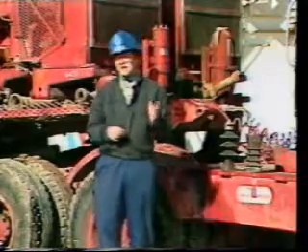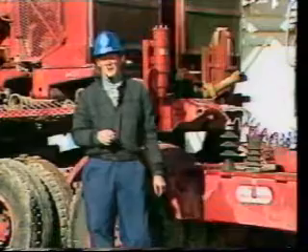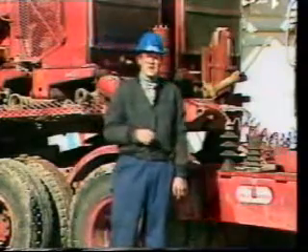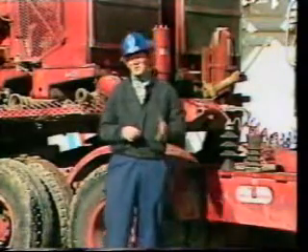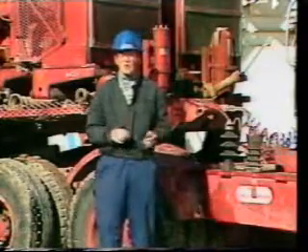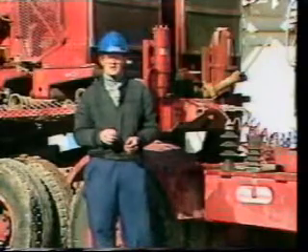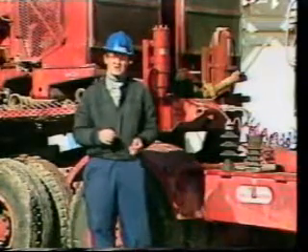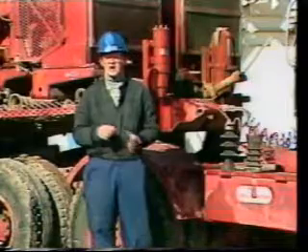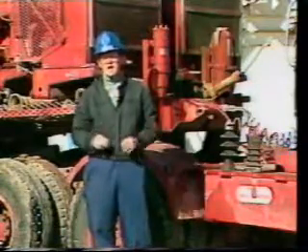When the second plug hits bottom, the pump pressure tells us that the cement has been correctly placed around the casing. With the casing securely cemented in place, the hole can be safely deepened without fear of losing circulation into shallow, low-pressured formations. As drilling continues, successive casing strings will be run and cemented concentrically to isolate and protect each